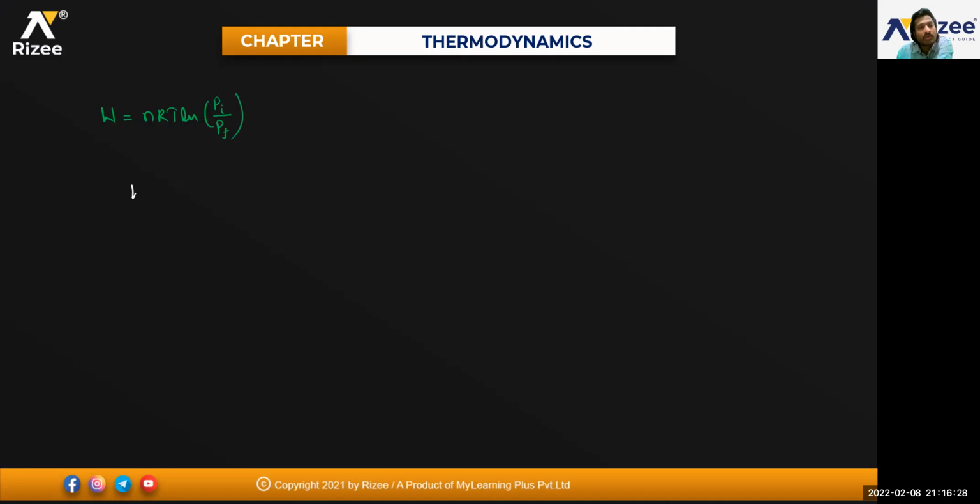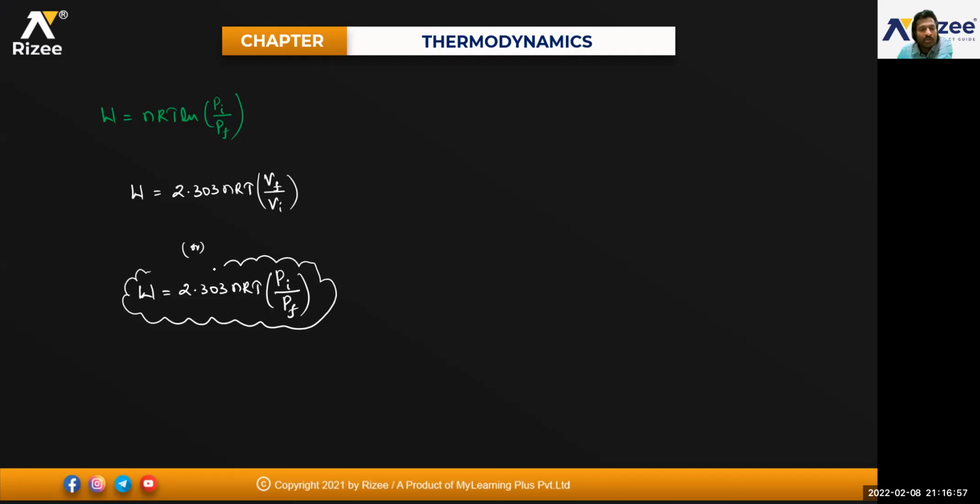Okay, if I remove the ln, I can write work done is equal to 2.303 nRT log of V final divided by V initial. Or I can write work done W is equal to 2.303 nRT log of P initial divided by P final. Clear? This is your work done. In an isothermal process, the work done is equal to this much.